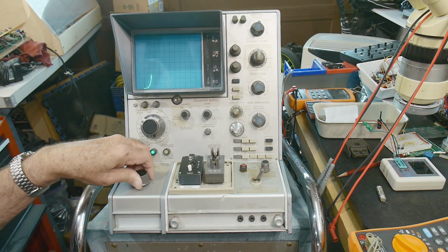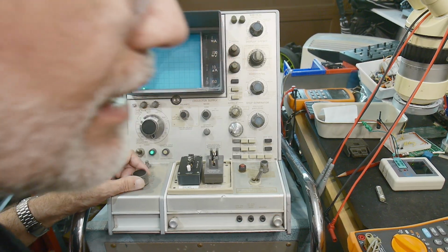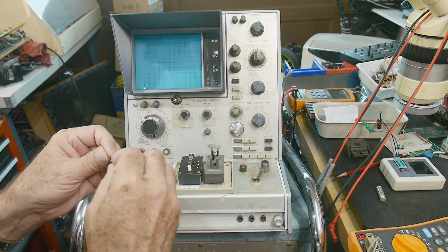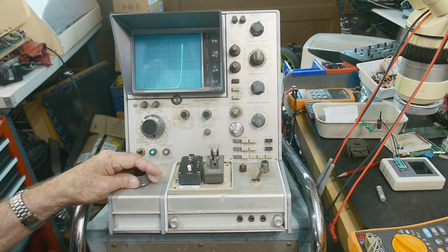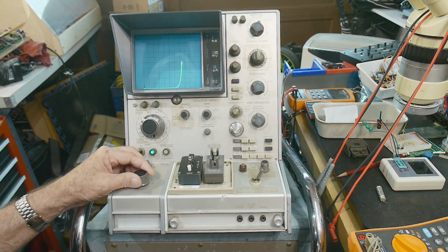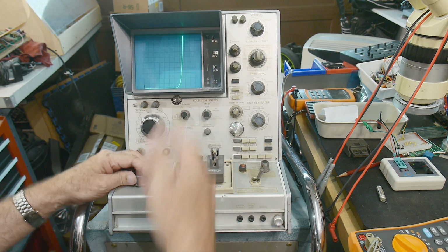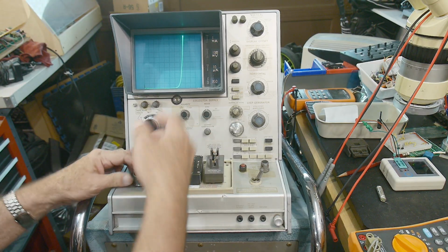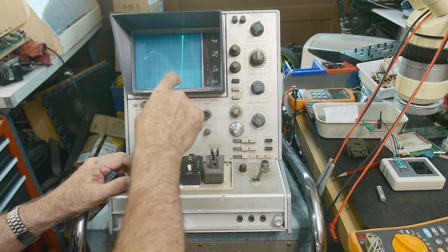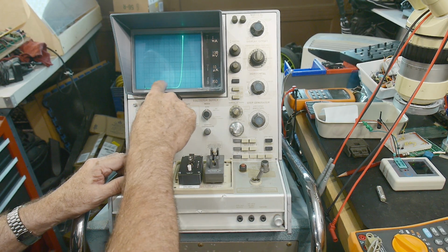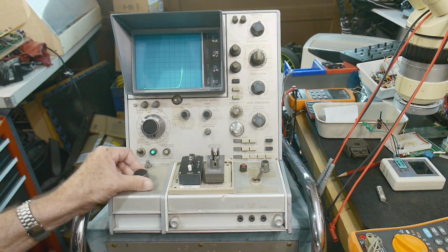Okay. Well, what about Zener diodes? Let's take a look at a Zener diode. I think this is a Zener diode. Let's put him in and sweep him. And oh, he looks just like a normal diode because I have him in the right way around, right? And so he's about 0.77 volts turn-on voltage. It looks like a normal diode, okay? This goes up to 10 milliamps, and it's 100 millivolts per division, so 1, 2, 3, 4, 5, 6, 7.7, about 0.77 volts at 10 milliamps.